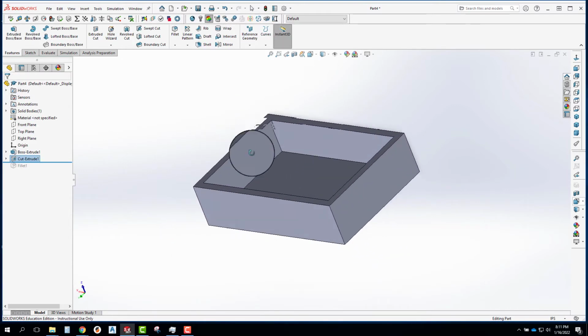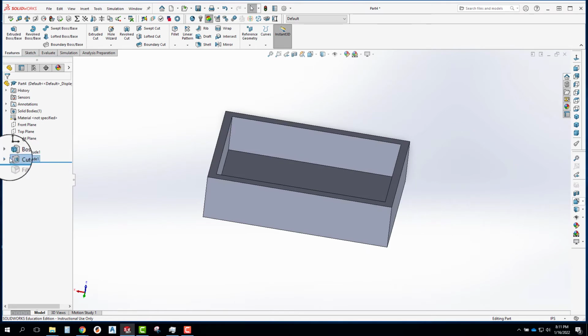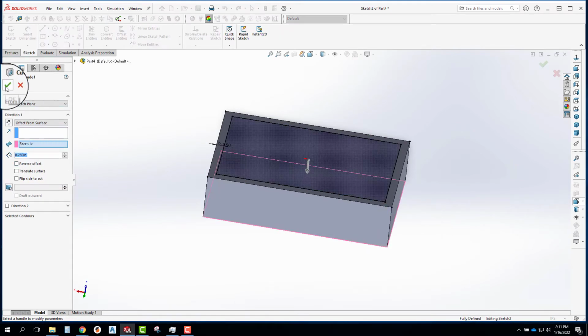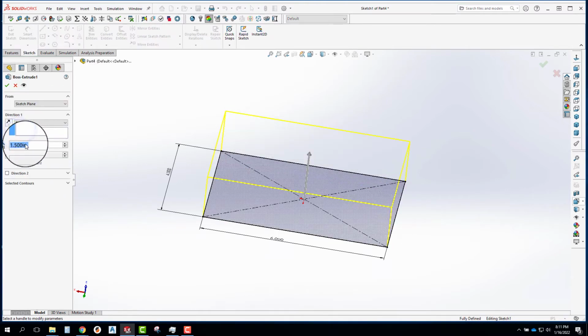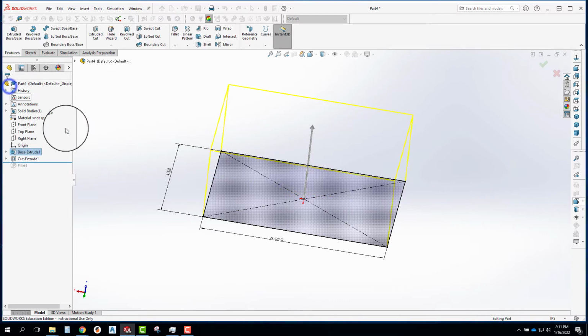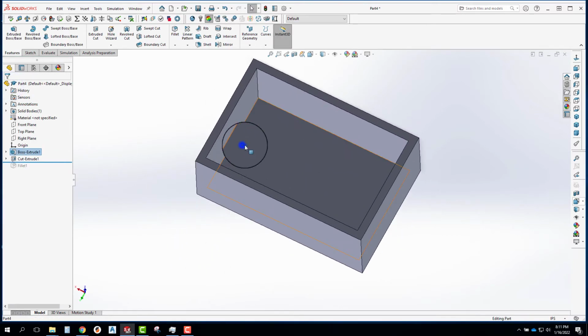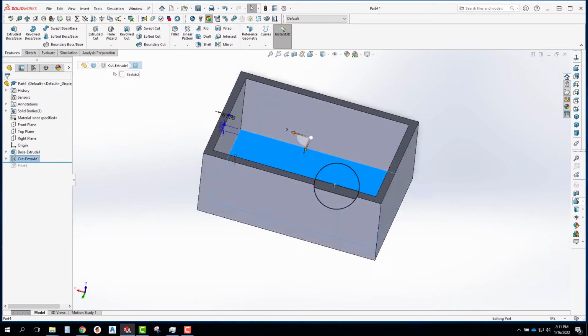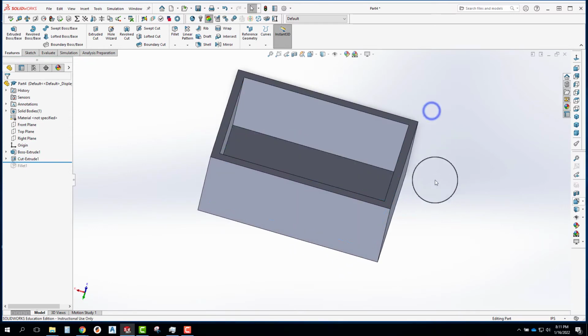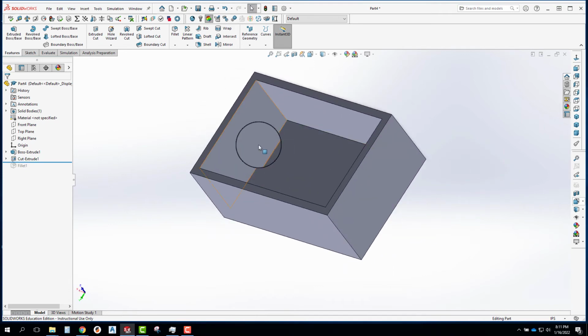And you can see I've got a box now. The reason it was good to use that offset from surface rather than doing the math for 1.25 inches is that, let's say I come back and change this so I made my box 2.5 inches. You can see that the depth stayed correct because it was always a depth of 1/4 inch off the surface. Okay, so that would have been one way to hollow it out, right?